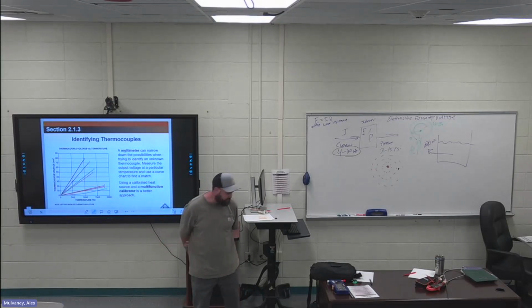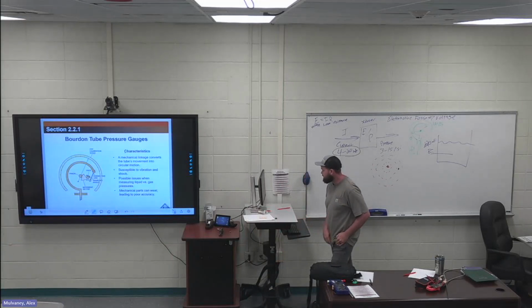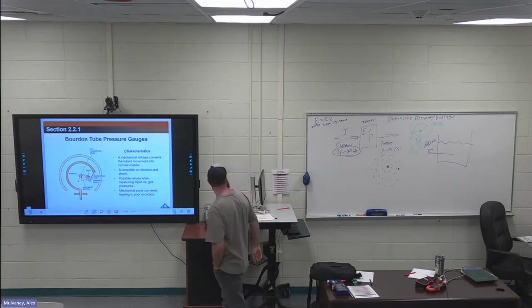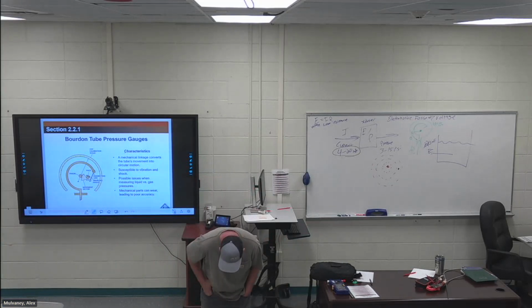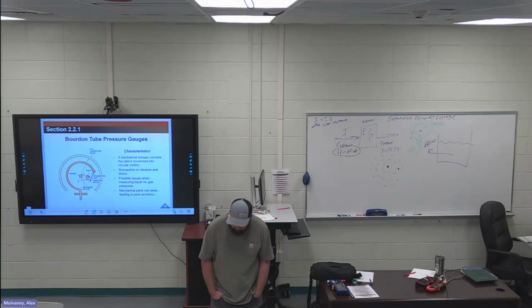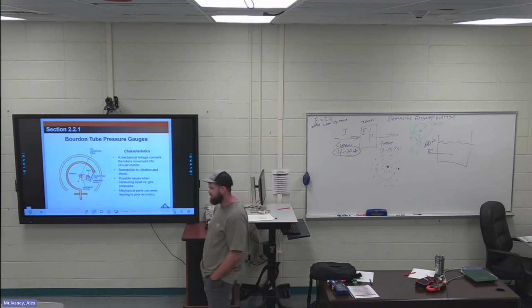Page 20, pressure detection. Feel like it's going into all the stuff that I've already talked about, and their picture looks just a little bit better than my picture. Two highlights that I'll talk about. 221, first two sentences are highlighted. One device that uses displacement distance to measure pressure is the Bourdon tube. In this case, however, it is the device itself that displaces. Key in on that. That's one of the higher missed questions on the test. It's the device itself that displaces.